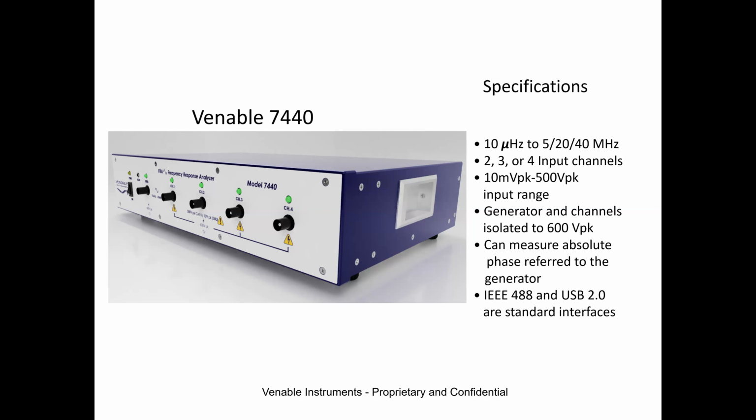The channels are also DC coupled. That's why we can measure down so low. We have what's called active DC offset cancellation on the input, since we're mainly interested in measuring the AC component of the signal and not the DC component. So we use that to reduce the DC so we can set our AC at an optimum range and get better resolution.